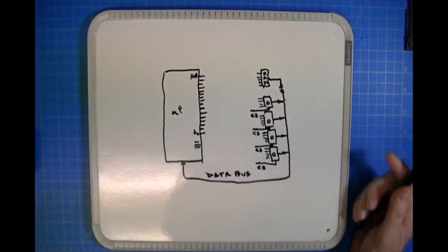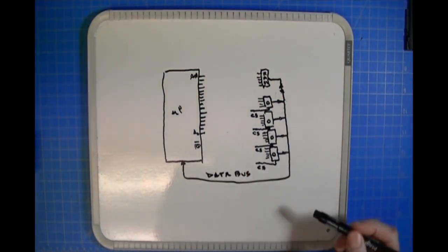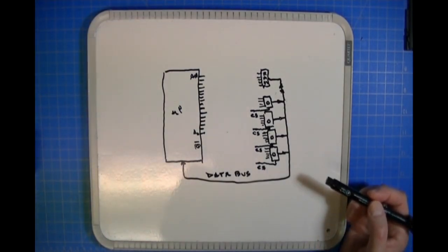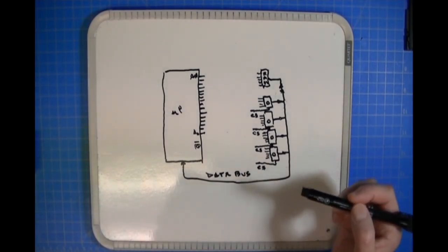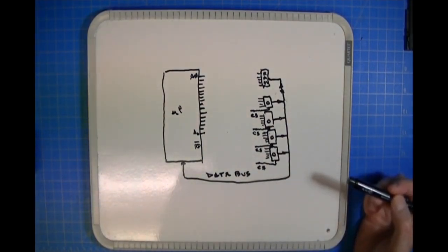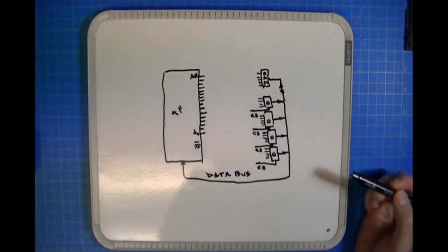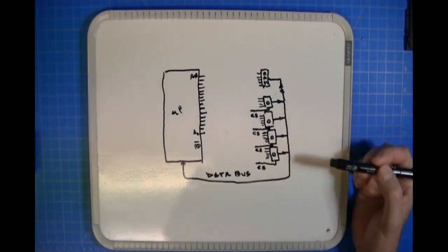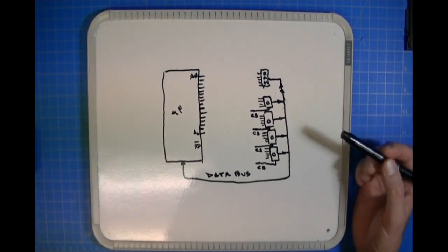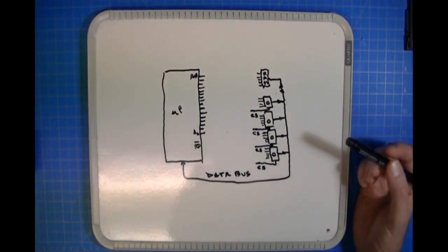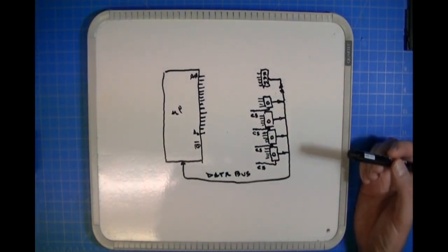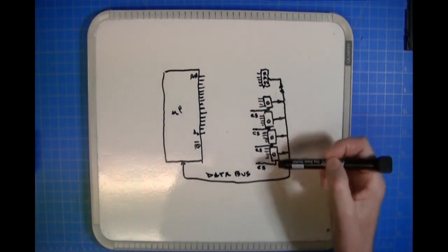The thing is, you can only read data from one EPROM at a time. So in order for an EPROM to provide its data, it has 2 lines. One is called chip select, and the other one is called output enable. Now, I didn't use output enable. As I said, I'm not trying to do a course in the functionality of memory. I just want to tell you why bipolar PROMs were created and what they do. So you have these 4 EPROMs, and then you have the RAM.